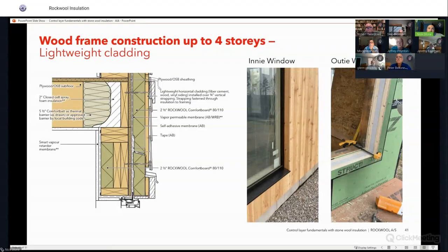So, the problem is hypothetically, yes, you want to have some kind of control layer on the inside, because otherwise the warm air is immediately going to let that vapor transfer to the outside and condense. But because it's a workshop, you could even just get away with plywood, just something to make a barrier. My suspicion is you're going to need to tape those seams, that way you have that continuity factor. But for a workshop, I don't see any issues with that, especially with a pellet stove, because it's pushing off dry heat. Because of those factors, limited use, dry heat, a reasonable control layer, I don't see why you'd have any issues there.